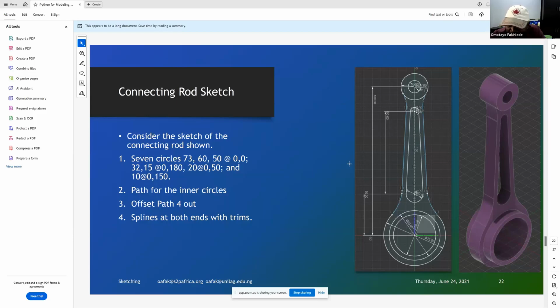And at every point in your drawing, the origin is always defined. So you will discover that when you have made enough specifications for a point to be reachable from the origin, because we have all the information about it, for instance, if there's a point that is 180 millimeters up from the origin, that is fully defined, because you go to the origin, you go through the z-axis, and you take 180 millimeters. That point is fully defined from the origin.